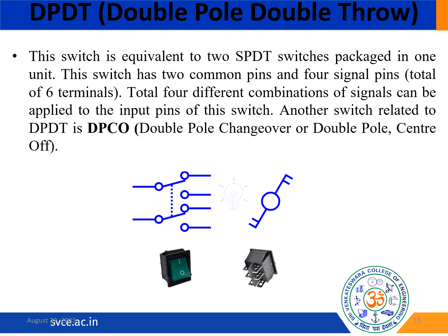When you consider DPCO, that is the double pole changeover switch, it is also known as double pole center off. Compared with the standard DPDT, the DPCO includes a central off position, so it also enables both the circuits to be disconnected simultaneously. This is useful for added safety or for idle states in control systems. DPDT switches are commonly used with two different electric circuits at the same time. While it has a common lever for both operations, it can be used for two different operations, and also for on and off positions.